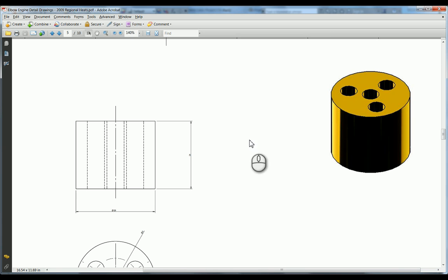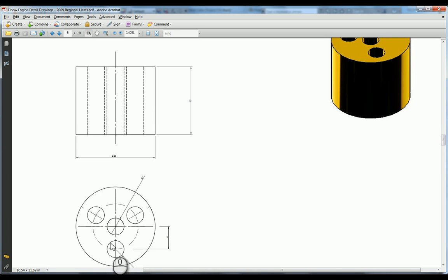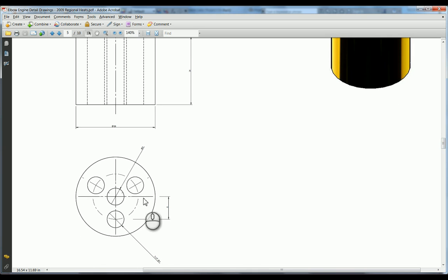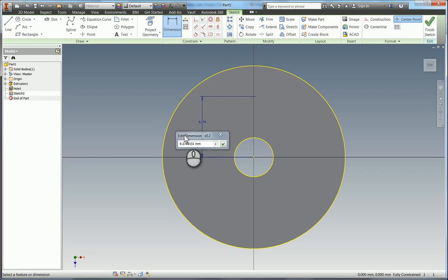If we go back to our PDF, we can see that there is actually a diameter here with 3 equally spaced 6mm through holes, and you can see that it's got a PCD of 16mm because we have this radius dimension here of 8. So that's quite handy that it's the same as the dimension I've just added. I'll change this to 8mm. You can now see just about that the point has changed to blue geometry, which means we are fully constrained as per down here.